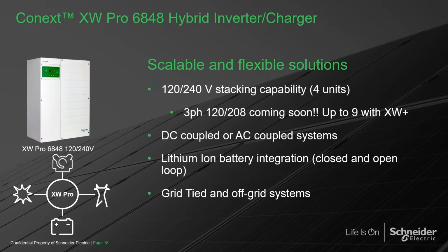When the inverters are together, we call it stacking. One becomes the master and the other ones become the slave. And now the inverter will operate as a single larger inverter. So for example, if I have 2 of these inverters, now I have a 13.6K system with a 30-minute overload capability of 17K. So everything will double. Continuous power will double and overload will double.